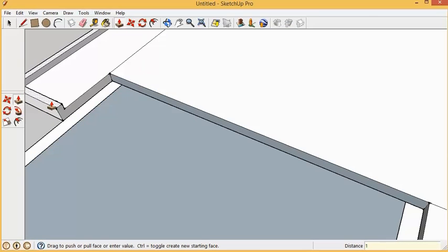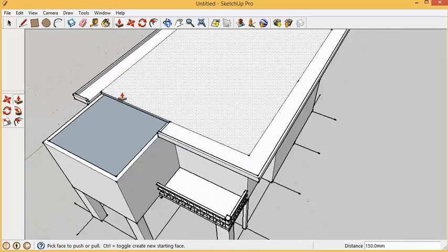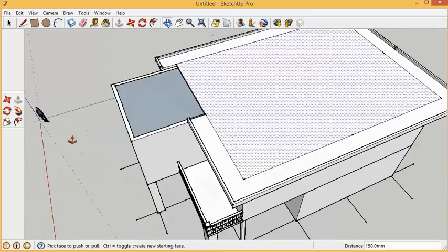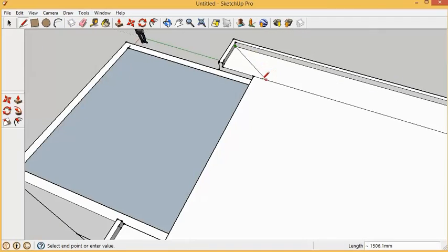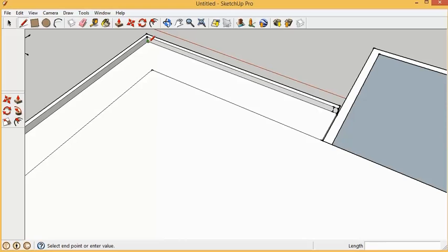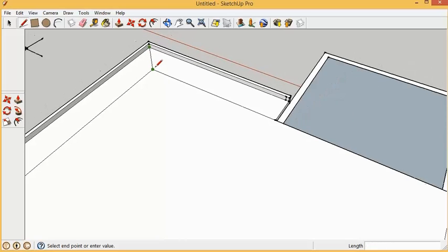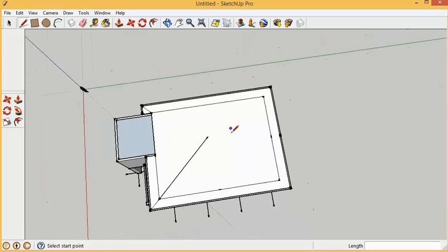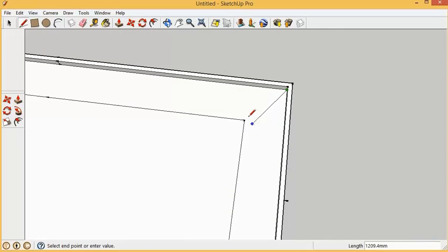Click and drag, and you can see how we can pull out. Instead of a color, we're going to skip over this and just use an image. Now, if I go to my desktop here, I should have something called woodfloor.jpg. When you import a texture, it's going to assume a size. So each one of these tiles is 1 foot by 10 and 3/4 inches. Click OK. Now we have it.